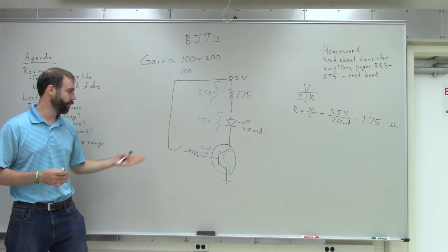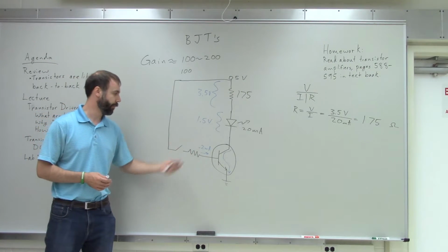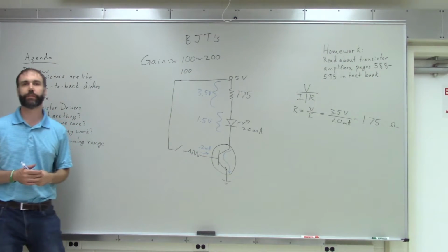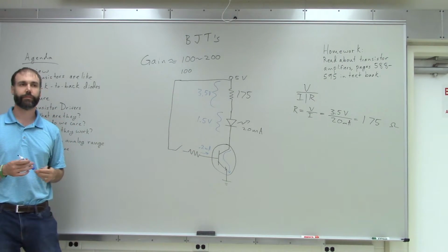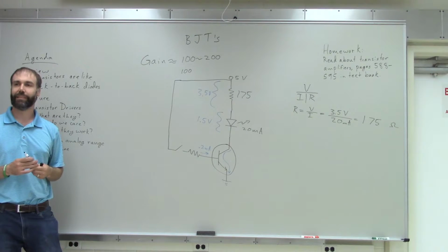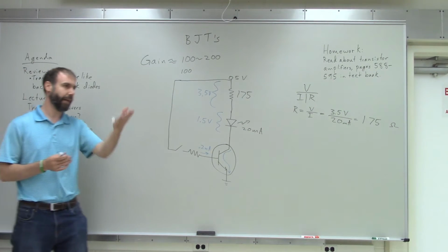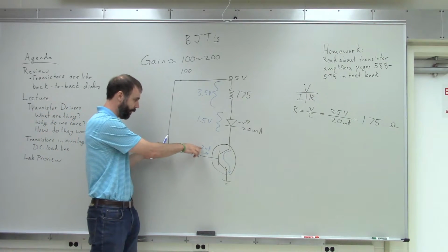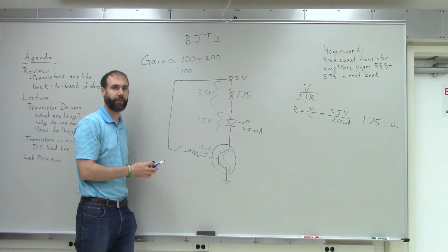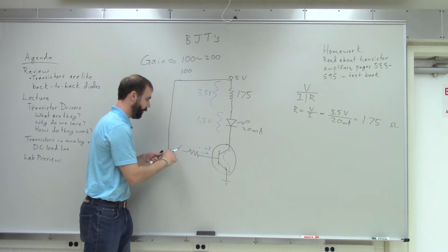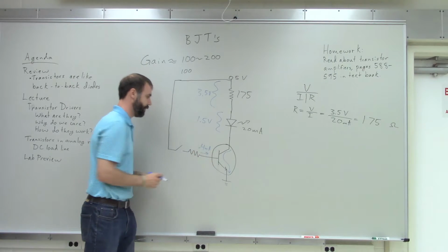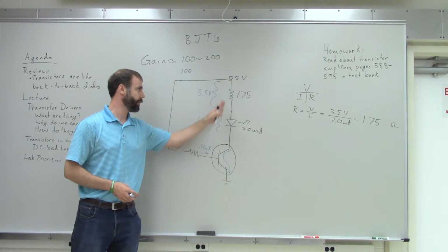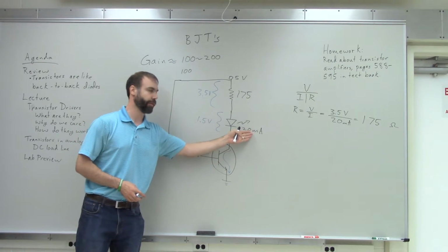So what can we do to sort of fudge this a little bit and allow the circuit to work even though we don't know exactly what the gain is? Yeah, double it, right? Sure. So we know that it would just be working if everything was exactly right when we had 0.2 milliamps going in. We could just double it, right? We'll put in 0.4 milliamps. The rest of the circuit is already set up to limit the amount of current to 20 milliamps.